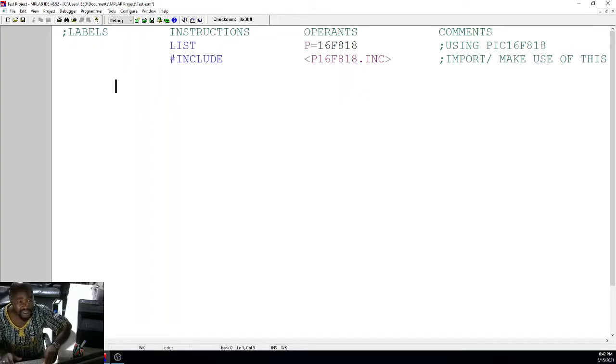Now, the next thing that you have to do is the reset vector. Origin 0x00. Sorry for that. Origin 0x00. Go to, let's say, initialize. So initialize is a label. Origin 0x00, that's what we call our reset vector.